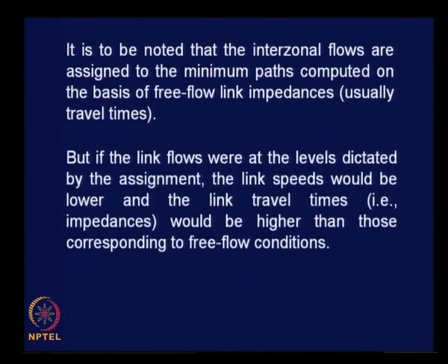But if the link flows were at the levels dictated by the assignment during the assignment process, the link speeds would be lower and the link travel times, that is impedances, would be higher than those corresponding to free flow conditions.